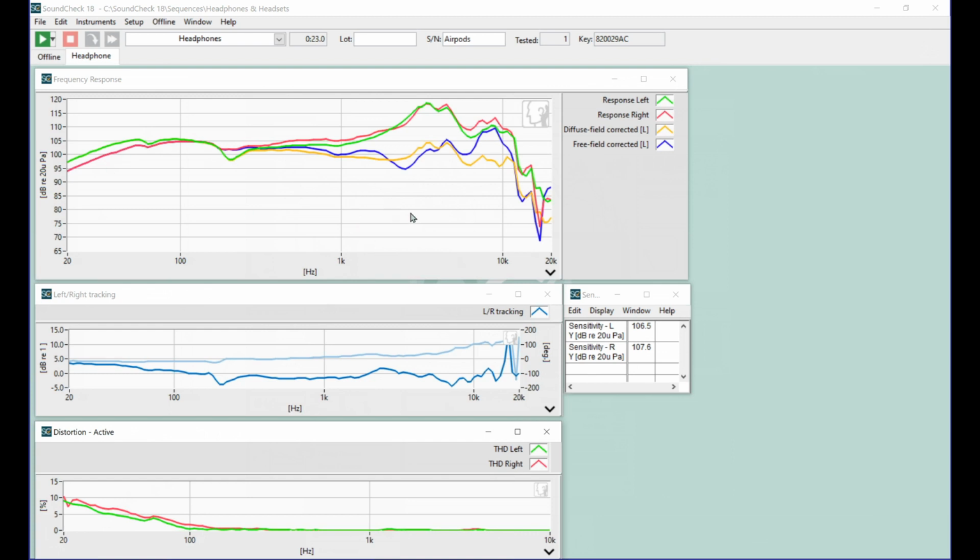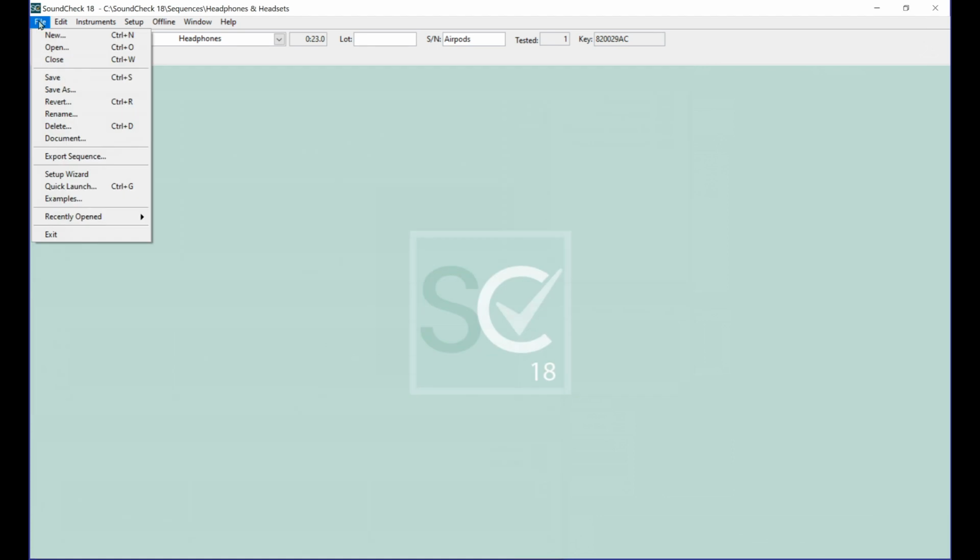And what I like to talk about in my distortion seminar is normalized distortion, where we actually take into account the linear response and how it filters the distortion response. And if we did that, you would see it would be well below 5%. So that's just kind of the nature of the high pass filter of the headphone. So pretty good headphone. And certainly if you want to put limits and calculate pass-fail results on a variety of things, you're more than able to do that.